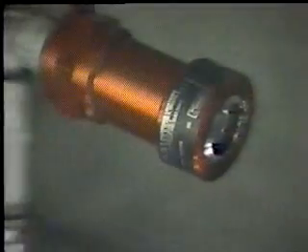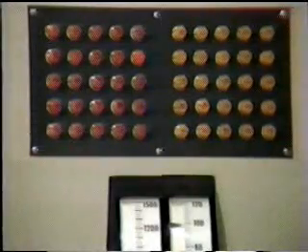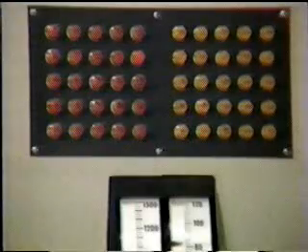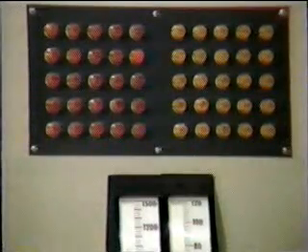The flame detectors Z398 and Z398-1 monitor the package for fires and will activate a fire extinguisher system if a fire is detected. Z398 and Z398-1 receive a signal from the flame sensors G399 that are located inside the package enclosure. The detectors are sensitive to ultraviolet light and will send a signal to the monitor when a fire is sensed. The monitor will transfer contacts in a relay, causing the malfunction light to illuminate and the engine to shut down. If a fire extinguishing system is included in the package, it will also be activated.